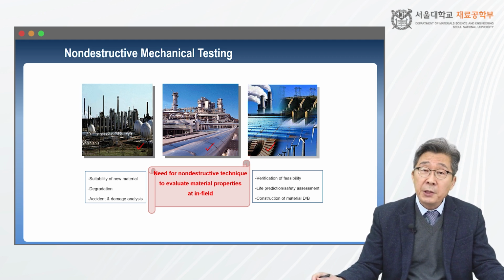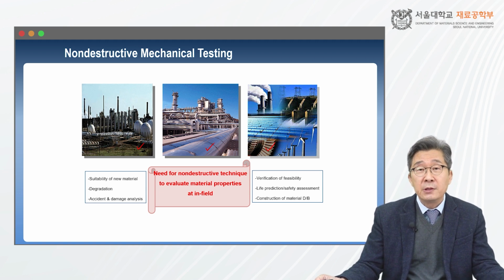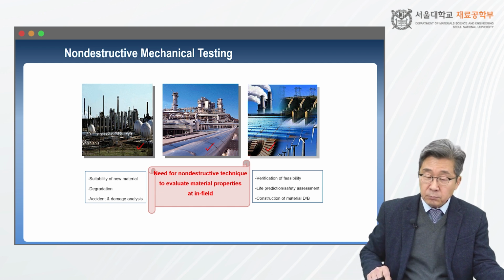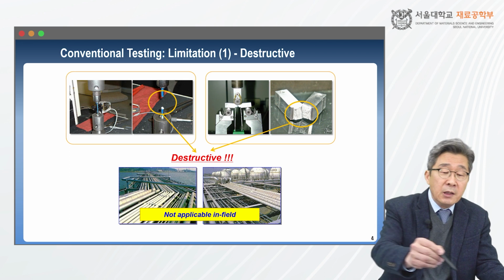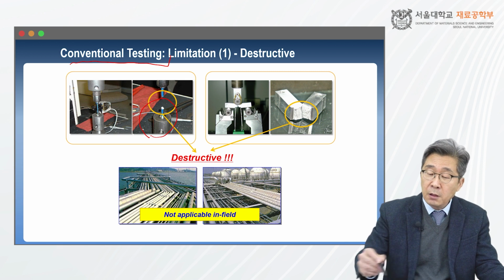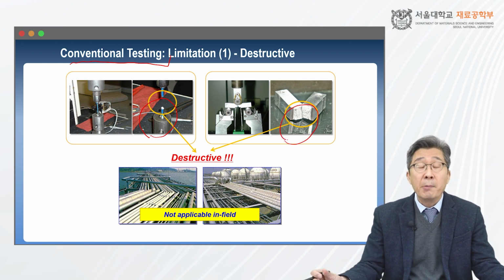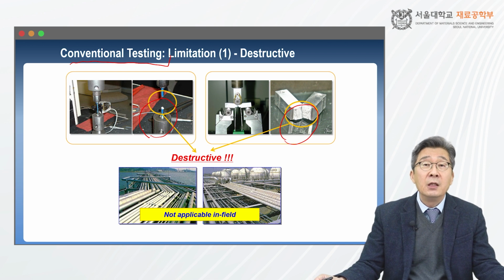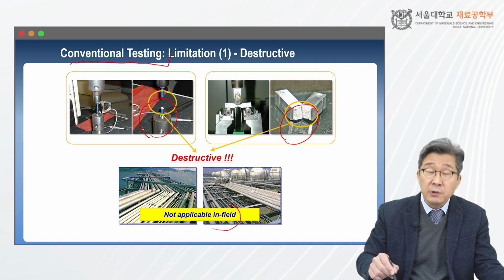Therefore, there has been a strong need to evaluate on-site components non-destructively. Therefore, we have noticed the practical applicability of instrumented indentation testing for in-field application. However, conventional testing, such as tensile testing or CTOD testing in the laboratory, as you can see, is destructive, which means it cannot be applied in field testing.